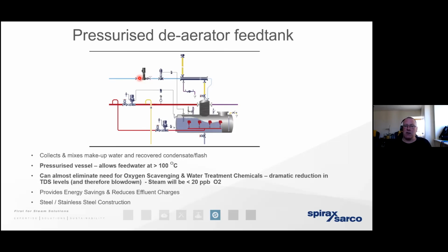The good news is those controls, the level control probes, the feed pumps, the TDS and the bottom blowdown, they can very, very easily be upgraded so that we can offer them the highest level of automation to ensure that the minimum amount of blowdown is being performed. And that's going to help us not only minimize any energy inefficiencies, it's going to help us to ensure that the steam condition that is being produced is of the highest possible quality.